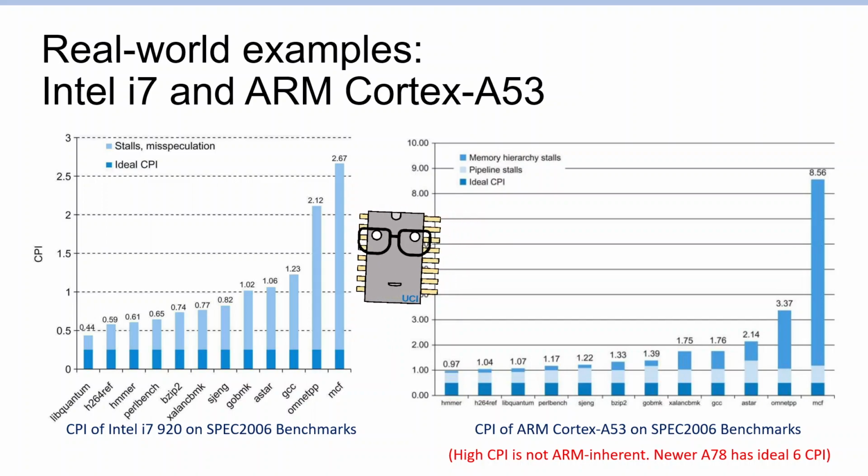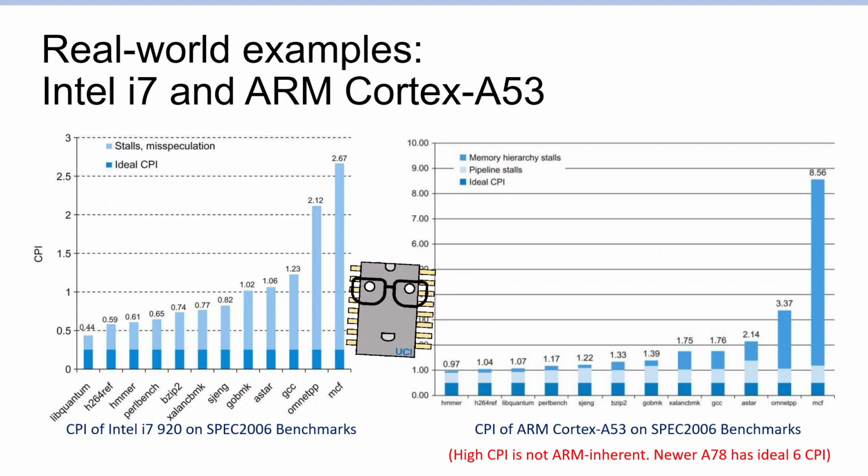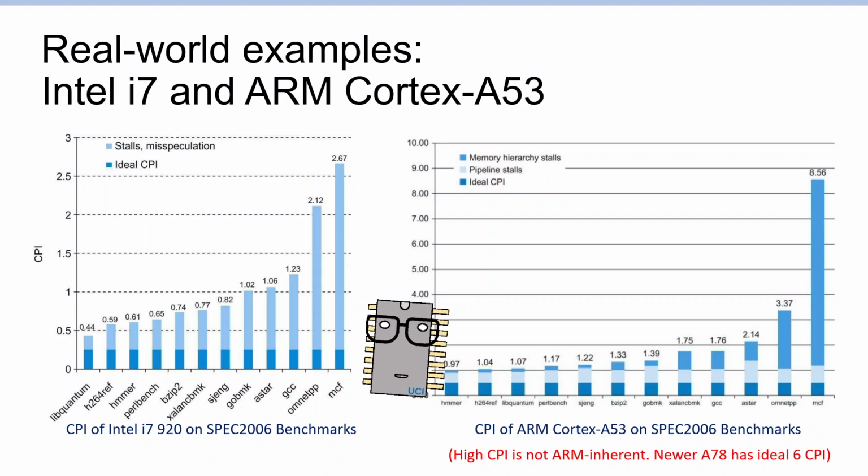Each of these bars shows the cycles per instruction. So if the average number of cycles per instruction is 0.25, for example, with the Intel example, we'll show that we are exploiting 4x the amount of ILP across the multiple execution units we have on the processor.